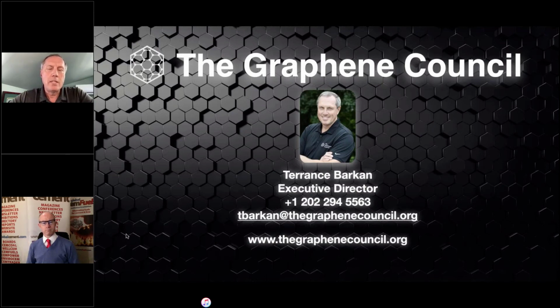A lot of graphene is made from graphite that's been exfoliated down to that several atomic layers of carbon level, and there are other methods of making graphene. Actually, almost any carbon source can be converted into graphene. So it just becomes a question of what type of graphene material you want to end up with. On the one hand, it's not terribly difficult, but there is expertise required to make sure you have a consistent batch of material that's actually down to that atomic level, and that's a little bit more of a specialist.